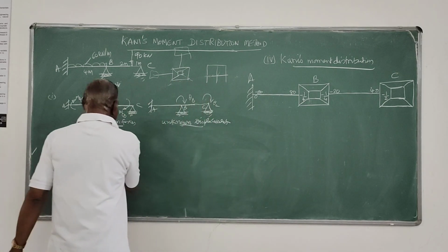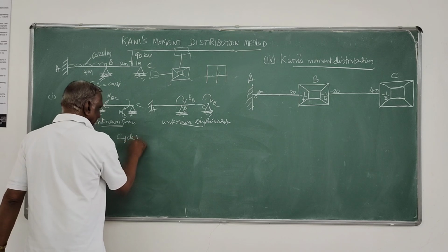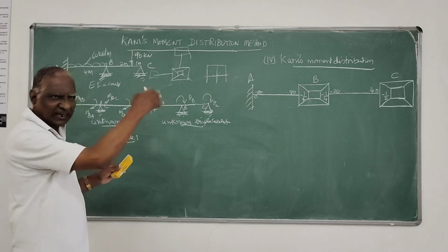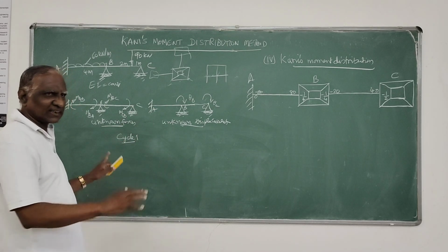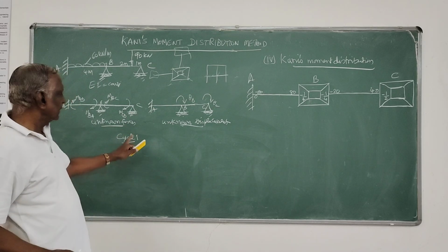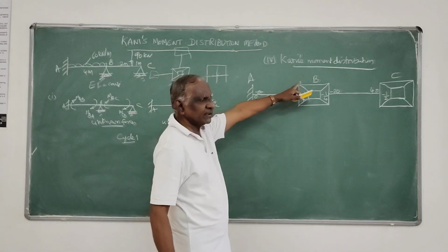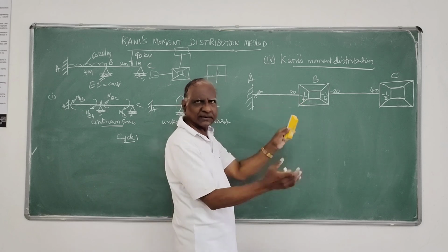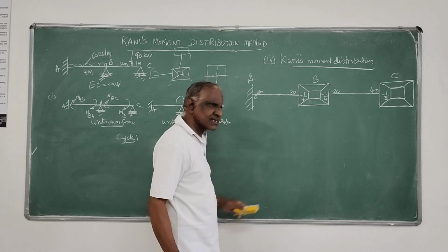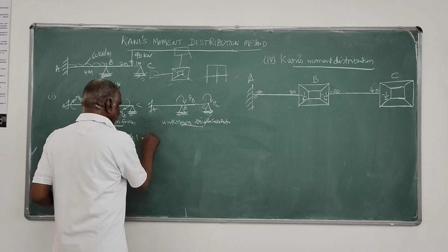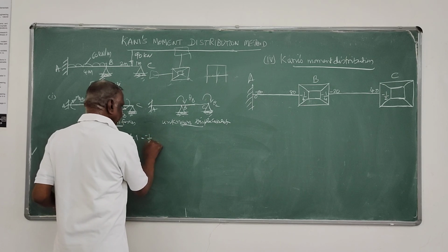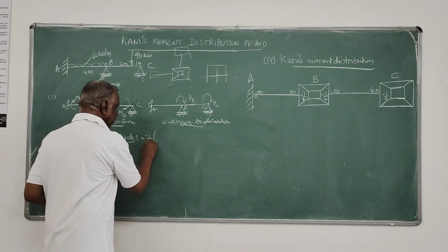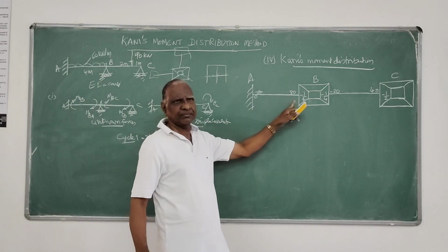That is our cycle 1. Separately I will indicate it by calculation to you. Even while answering, you can take out, write a margin and do all this calculation only for reference purpose. So cycle 1 in the joint B, rotation factor or rotation moment, that is rotation contribution moment. It is first rotation factor, which is minus half, not minus half, minus 1 by 4 for BA.